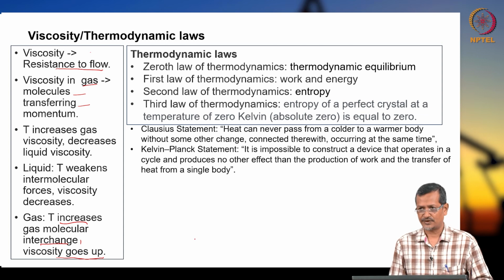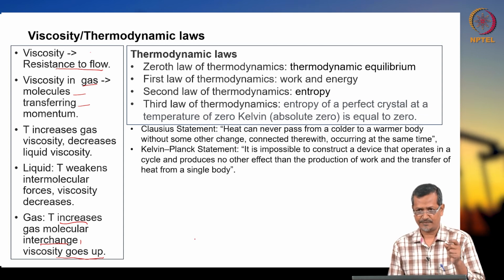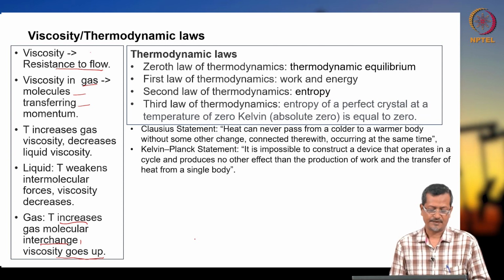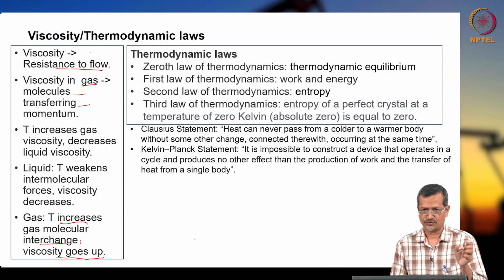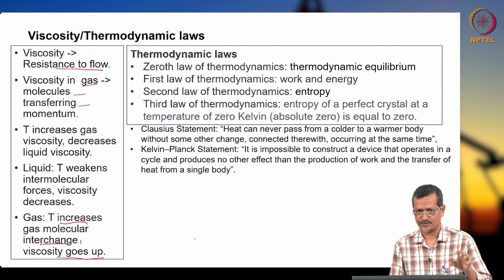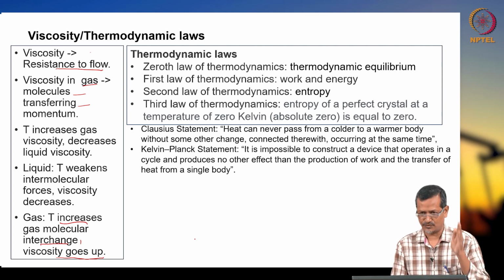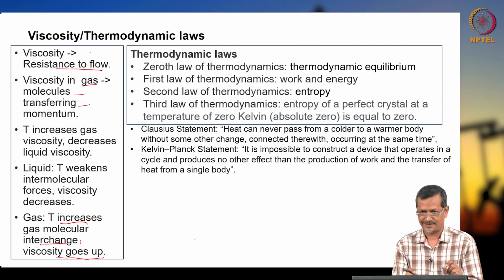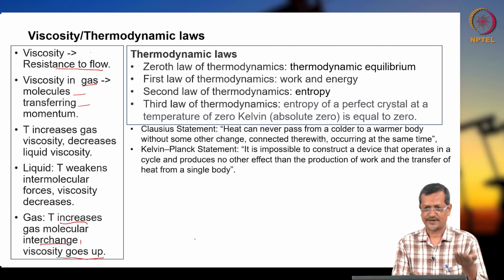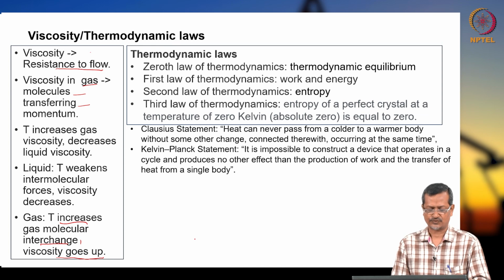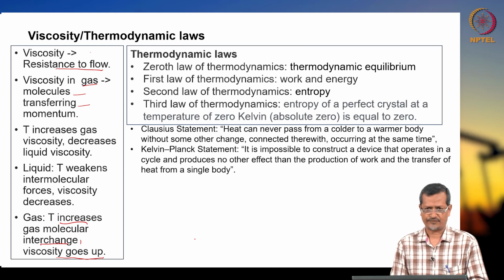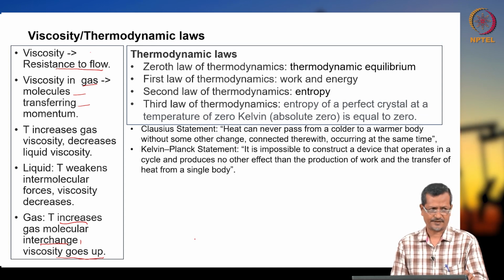So, molecules will be transferring momentum and viscosity will go up in gas, but in liquid just the opposite happens, because molecular attraction forces are reduced by temperature, so molecules do not hold on to nearby ones. In that way viscosity will decrease. For further details, go through any undergrad textbook on viscosity.